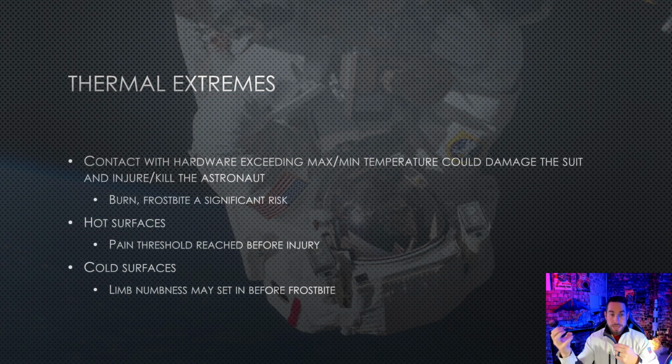Because there's this risk of burn or more likely frostbite, a thermal evaluation has to be done on every piece of hardware that's used in the EVA environment. So you have to make sure that it's not going to exceed maximum or minimum temperature requirements. So it'll stay within a range, and it'll decrease the likelihood of burn or frostbite.